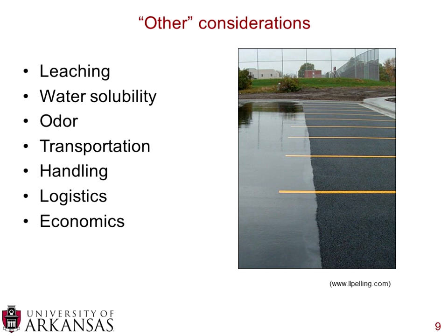Those are all the performance characteristics, but then there are also several other considerations. Leaching is always a concern. Whenever you're putting a new material into a pavement or pavement structure, you're always concerned about, as the rain falls down and the water moves through that paving material, does that leach any material out of the pavement, because then all of that water with leachate goes into the ground and into the groundwater table. You need to be careful of that.